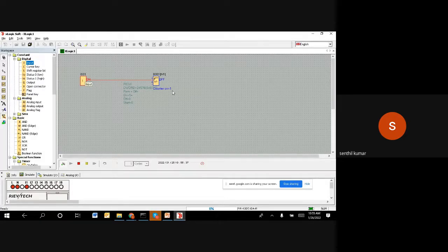As we said, for any counter, the value has to go high, then drop to 0, then go high again. Whenever it goes through a positive edge, you can see the small arrow going up in the picture, meaning the value goes from 0 to 1, that is where the count starts. When it stays on, it won't count again. Maybe a bottle got stuck somewhere and the sensor is sensing it, but it should not count 1 2 3 4 5 6 7. That is why they made this mechanism.